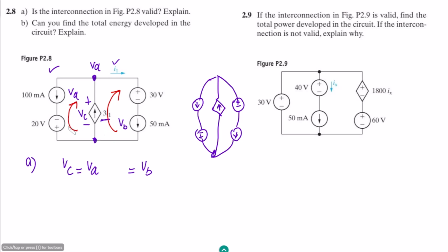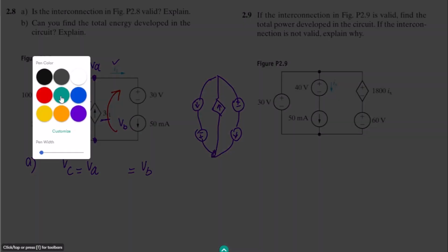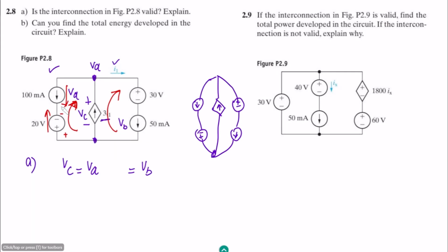Okay, so we can see here that this is negative, this is positive, and as the direction of this current and this current, these two are opposite to each other, one current is flowing through it like this one, and for the other one, the actual direction is this one. So the polarities of both of them will be opposite to each other. So the polarity across this one will be what? It will be negative and positive, because this is positive negative, it will be negative positive.